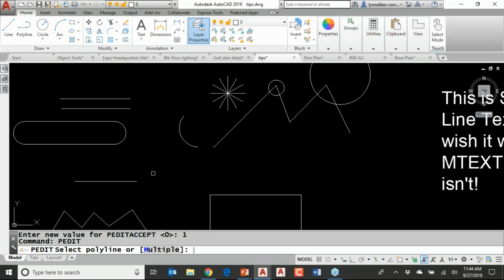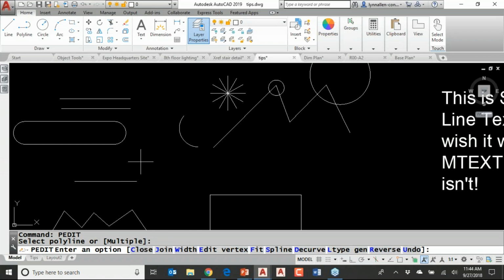So let's go back into PEDIT. You try it one more time. Pick it. Look at that, it didn't ask me the question. It just assumed I wanted to turn it into a polyline, and it went on its merry way. It's a fabulous, fabulous, beautiful thing. I will warn you that we're pre-programmed to hit an extra Enter to get past that question, which now will actually kick you out of the PEDIT command. So you do have to readjust your strategy. But nevertheless, it will never ask you that question again.